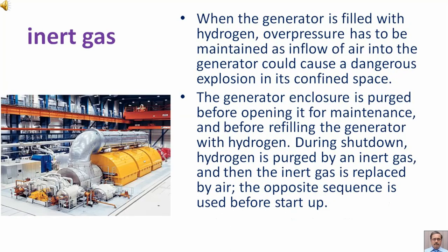When the generator is filled with hydrogen, overpressure has to be maintained as inflow of air into the generator could cause a dangerous explosion in its confined space.